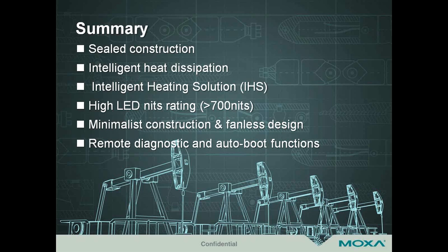And what happens if the unit overheats? That's a complex question. We like to say it won't, at least on any temperature recorded on the planet Earth. But if it does, it has an overheating mechanism where it will shut the computer off, at which point you can capitalize on an auto boot function once it reaches a temperature amicable and safe enough to operate without damage to the computer. That's what the auto boot function's for. But that question speaks to the importance of having a computer that has an insulated LCD screen and can operate well over 50 degrees Celsius.